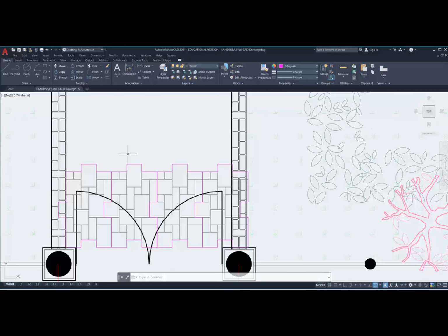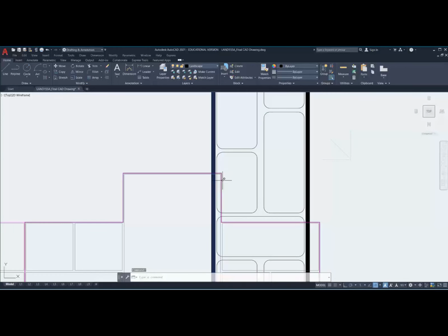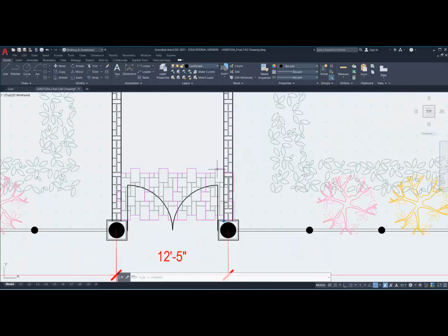You work on the principle of the tile that's coming in, along with the space that you're going to do, and make sure it fits perfectly. And here it doesn't fit perfectly. Look, this line coming through here interferes with that corner. So I would move that line over, and how far over? To that magenta colored line, so that I also have a grout position there for the sand or whatever you're going to fill it in with, and it fits perfectly.